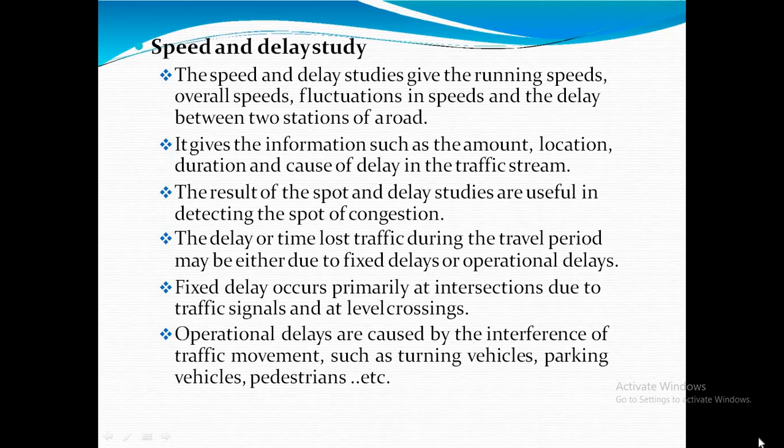And these are the uses of a speed and delay study. The speed and delay study gives the running speed, overall speed, fluctuations in the speed, and the delay between two stations of a road. It gives the information such as the amount, location, duration, and causes of delay.